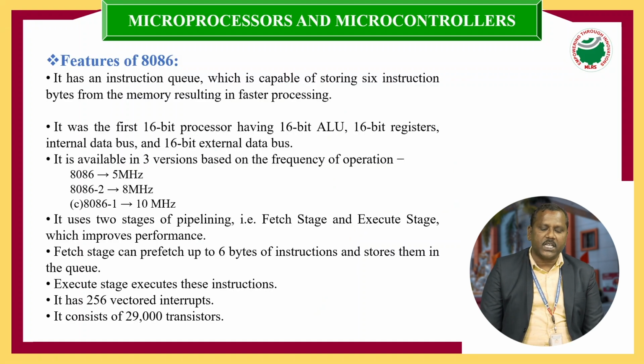Next topic is features of 8086. 8086 is a 16-bit microprocessor. It can transfer 16-bit data at a time and it is available as a 40-pin IC dual in-line package. The memory of 8086 is 1 MB, 1 megabyte. And it has 20 address lines and 16 data lines.